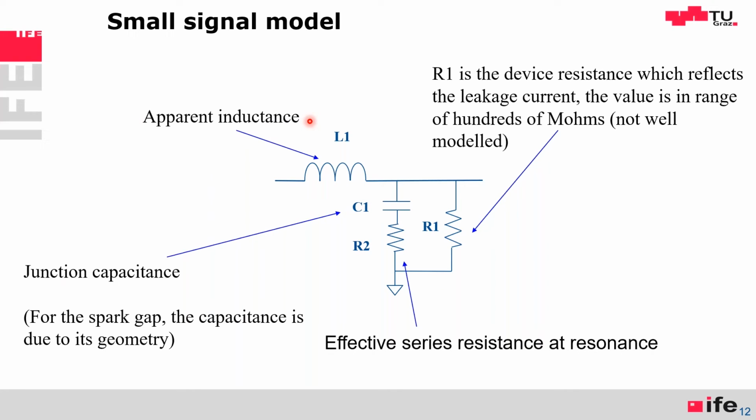And I really want to point out this is the apparent inductance, because everybody says, oh, this capacitor has an equivalent series inductance, ESL, and it has like 2 nanohenry, or we say 1 centimeter of wire has 5 nanohenry of inductance. Mathematically, that's completely wrong. You cannot assign inductance to anything where you don't know the complete current path. So a short piece of wire cannot have an inductance. Same with a capacitor.